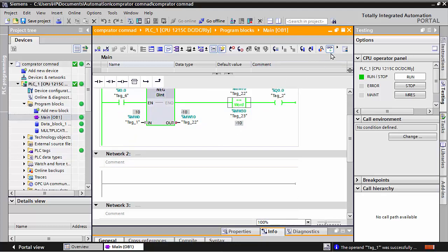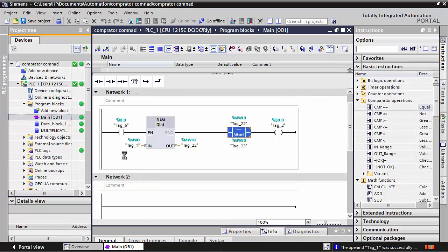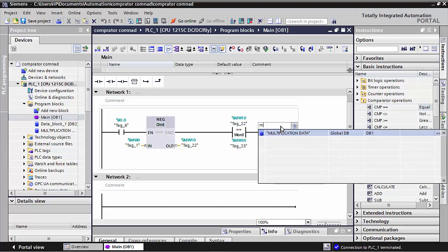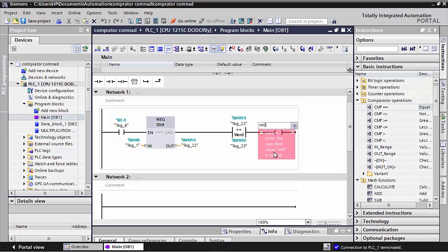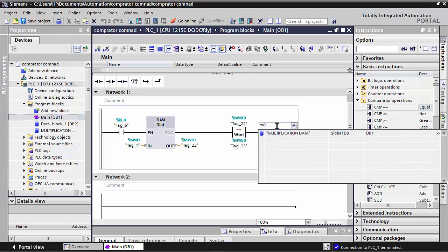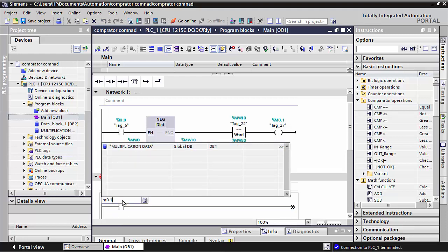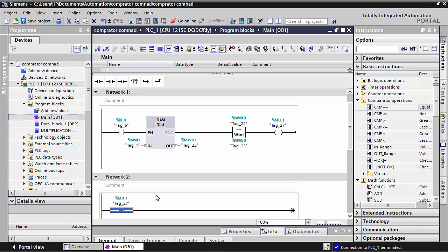And next, how you like to do the program inside the PLC depends on your own logic. You also stop it here in offline condition, and here you can use this one in internal memory M0, for example, sorry, M0.1, and that will be on. And after you can use here any instructions, M0.1 when on.